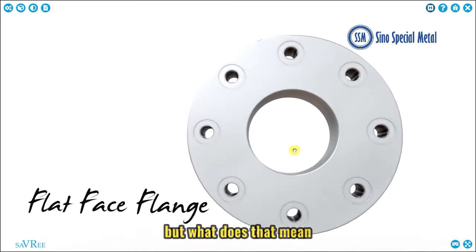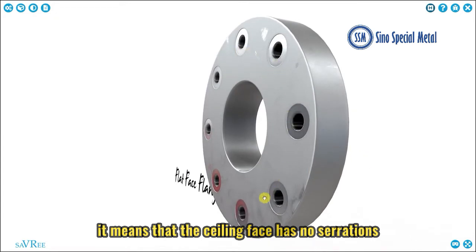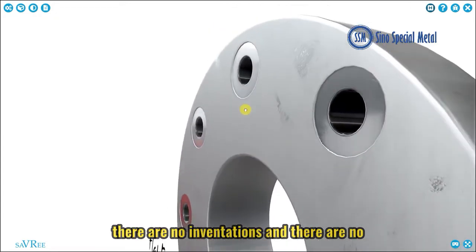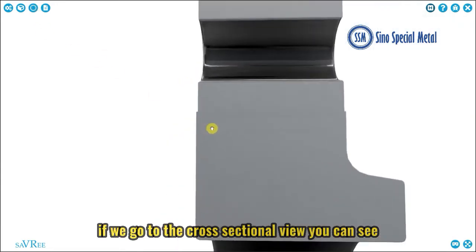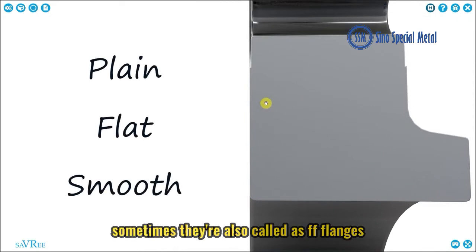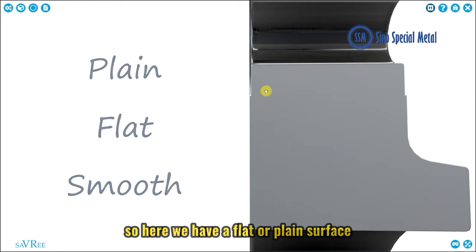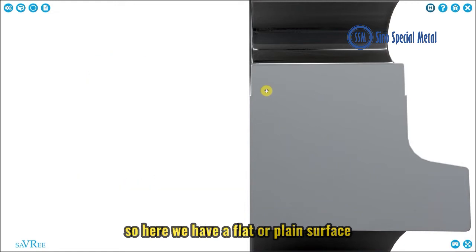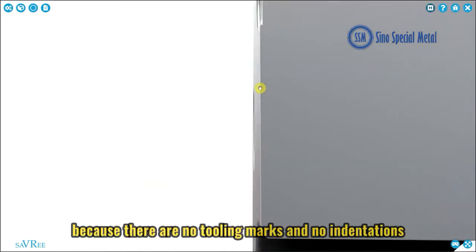But what does that mean? It means that the sealing face has no serrations, there are no indentations, and there are no tooling marks. If we go to the cross-sectional view, you can see the face is plain. Plain face, flat face, sometimes they're also called FF flanges. These terms all mean the same thing. But we're not talking about faces, we're now talking about surfaces. So here we have a flat or plain surface because there are no tooling marks and no indentations, etc.